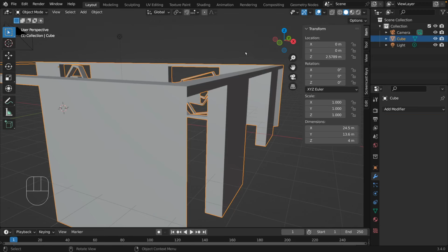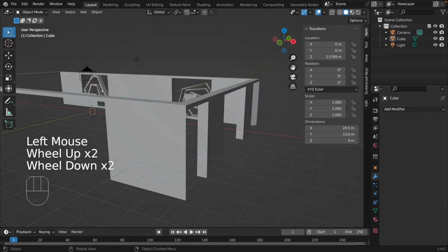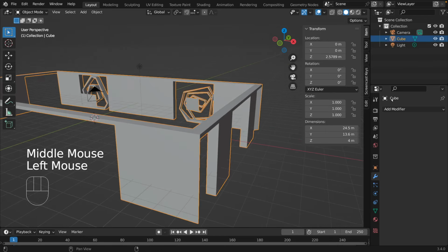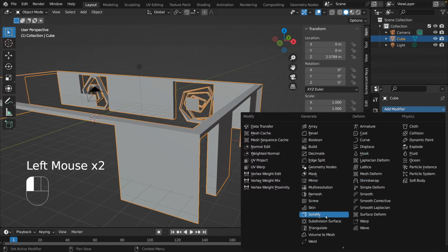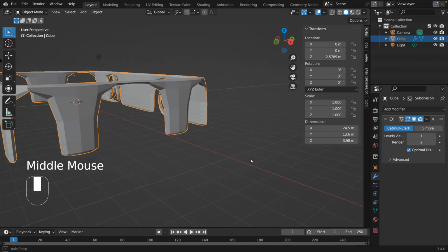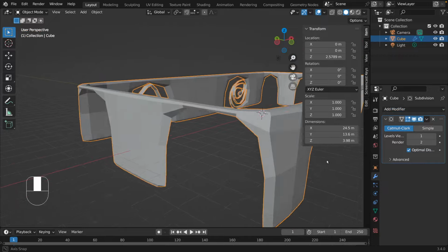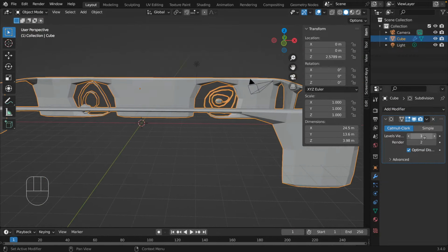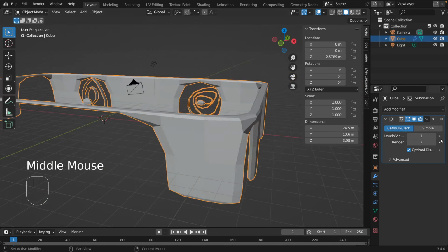Yeah, I changed my mind. I think the bevel modifier has sort of a bug, because I got a pretty messy shape, and the results I tried multiple times are not good. So I changed my mind. I think the subdivision surface gives a much better shape than the bevel modifier. It gives you a sort of low poly shape, so I'm going to increase that, because that is pretty crude.